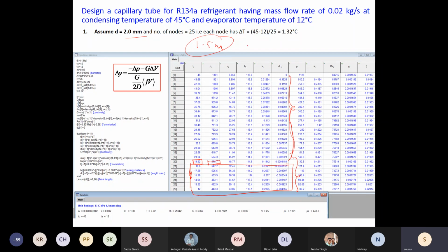Then see, the evaporator temperature can be lowered by increasing the mass flow rate through the compressor, because as I told you, the operating condition of your system is decided by, of course, the load and how much your compressor is sucking in. So if your compressor is sucking in a lot of refrigerant, you can lower the evaporator pressure and hence the temperature.